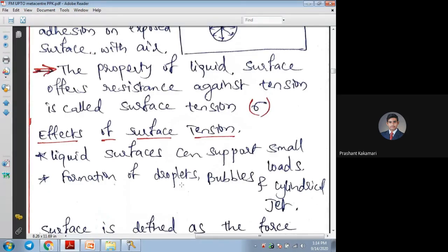Why is it falling in the form of droplets in spherical form? Because it has more tensile force, the surface tension forces. All the molecules of that water are trying to be in a spherical form, in contact with each other. They are not trying to sprinkle out or be attracted to the atmosphere more. So whenever it flows in droplet form, due to the surface tension itself, the liquid holds a spherical or other curvature form, and the molecules do not go away until we overcome that surface tension.